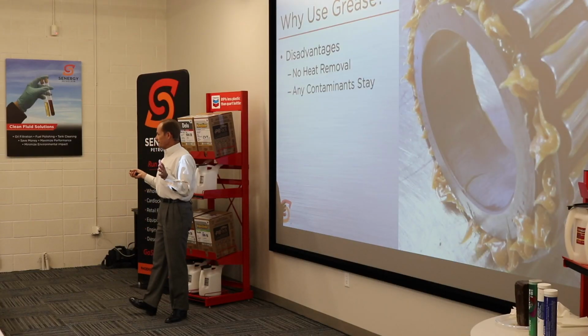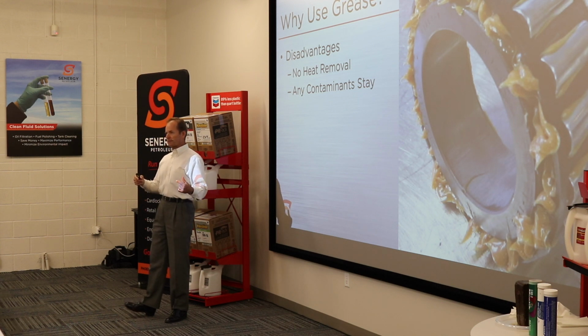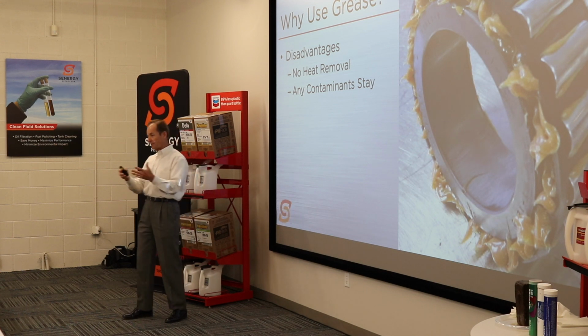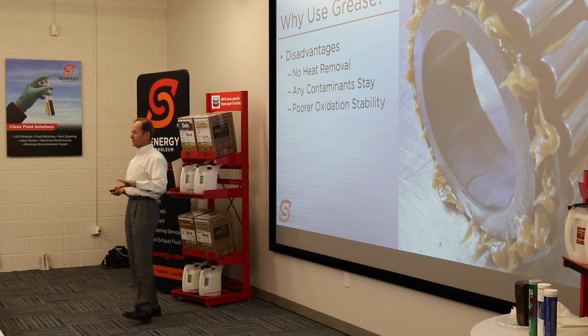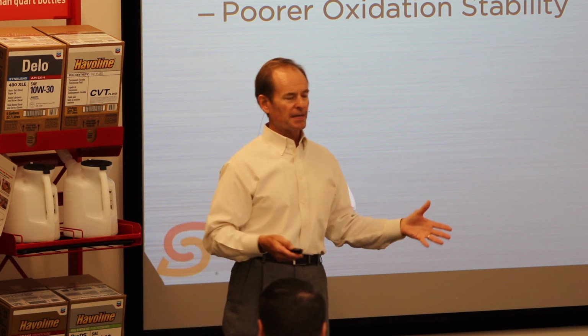Second, when you do get contaminants in your grease, they're staying there. You don't have a flushing process. With oil, if some contaminant gets in, you get a chance to get your contaminants flushed out. Poorer oxidation stability, this ability to resist breaking down.